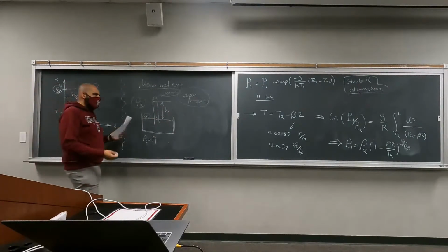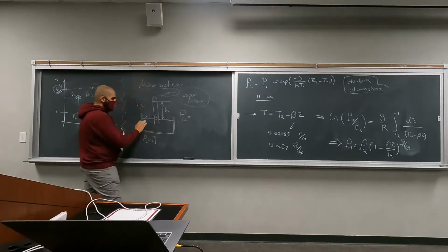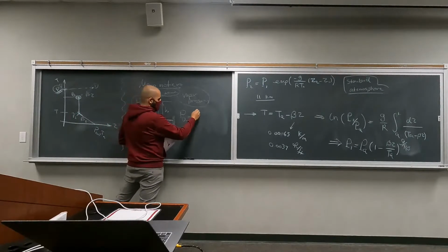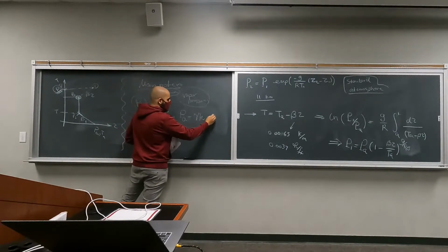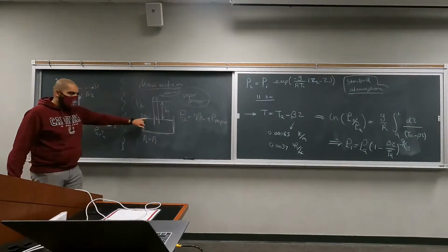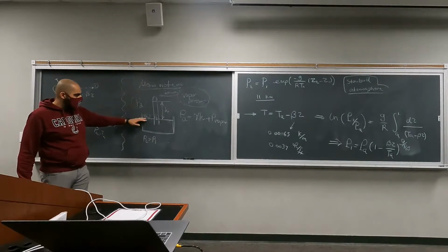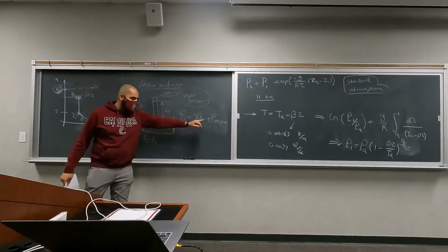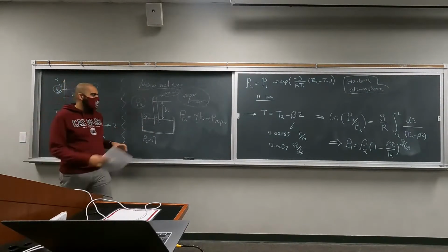Based on this, the general formulation is that the atmospheric pressure is going to be your gamma multiplied by this height plus the vapor pressure. The pressure at point 2 and point 1 are equal. So PA plus P2 has to be equal to P1 plus gamma H plus P vapor. P1 and P2 will cancel out because they are the same.